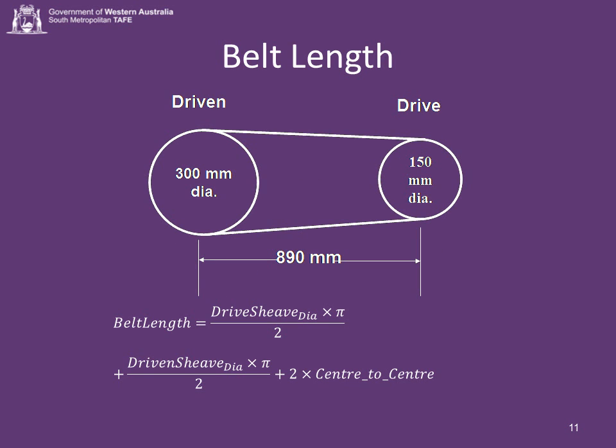Often, when a mechanic has to change out belts, the number of the belt can't be read, or the belt is broken or missing. So what should you do? Take a tape measure and wrap it around the sheaves to get the belt length. It's not a very accurate way to determine the length, so usually the mechanic ends up taking a number of different size belts, hoping to have the size that will fit.